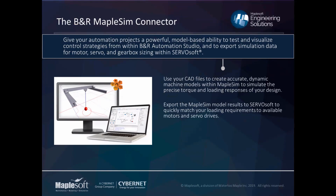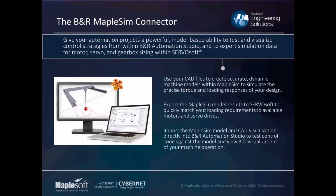Now that we've gotten our precise loading requirements and torque requirements from the MapleSim model, we can bring that into ServoSoft and then just pick the motors off the catalog that are going to work for us with a much higher degree of confidence than was done before. And then if you want to take it a step further and really get into that virtual commissioning, you can take that MapleSim model, we export it to B&R Automation Studio, and then we just use that as a test platform for the PLC code that you're creating in B&R Automation Studio.